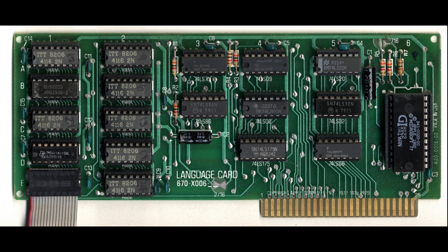As you can see on the photo of the original board, on rows 1 and 2, the leftmost two rows of chips, there are 9 dynamic RAM chips, 1 bit by 16 kilobytes. So 8 of these are needed to compose the 16 kilobytes of RAM, and one of them needs to be extracted from the Apple II motherboard and inserted in an empty socket on the board. And as you can see on the bottom left, there is a ribbon cable with a header that goes into the socket of the chip we just extracted.